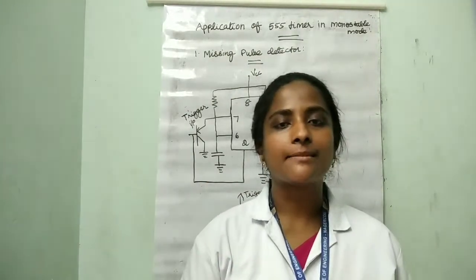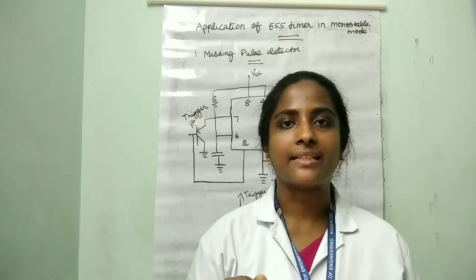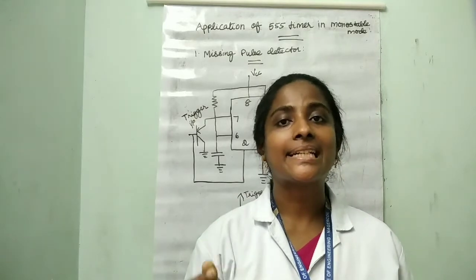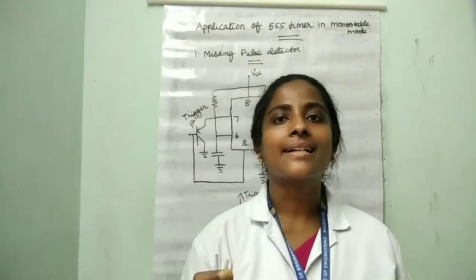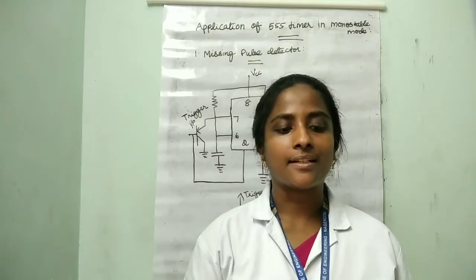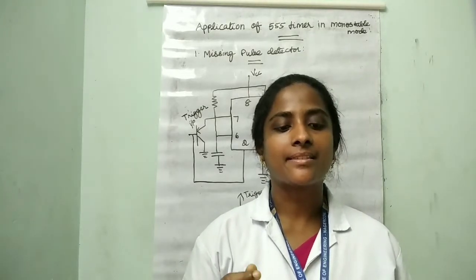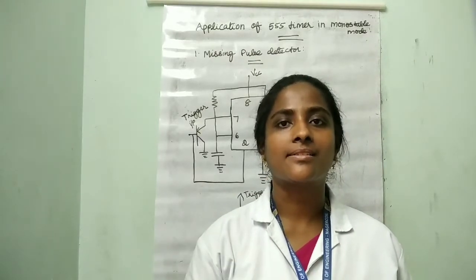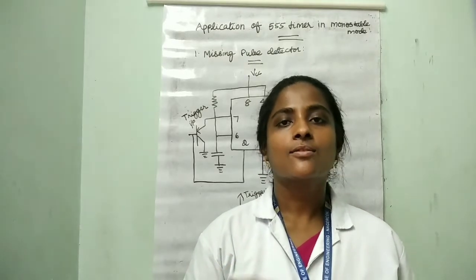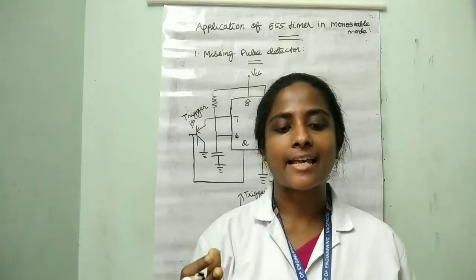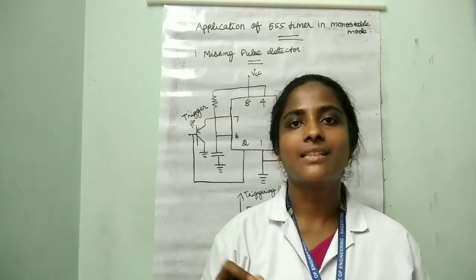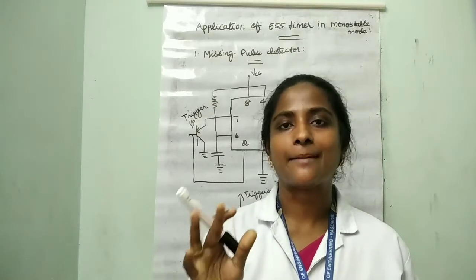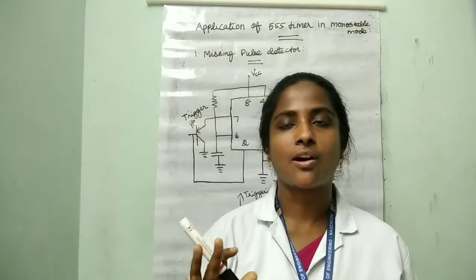If a pulse is missed, the triggering input is high, and the transistor Q goes into the cutoff region. Now the 555 timer is in the normal state of monostable operation. So the output goes low after a time period T of the monostable, that is the monostable period.